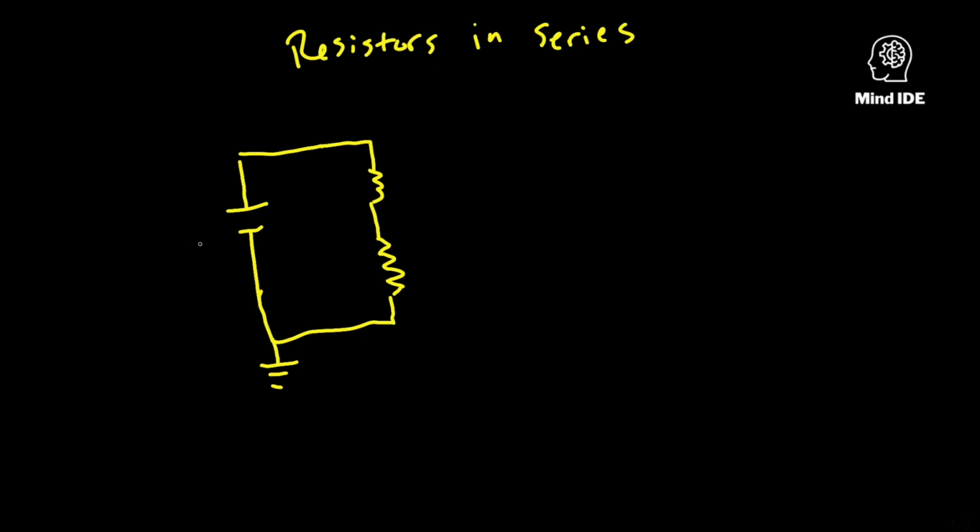So this is your voltage source right here, which we're doing resistors in series with a DC voltage. So you can think of this as like a battery. We're going to call this 5 volts. And then resistors are kind of this sawtooth looking thing. That's how you identify them in a circuit. So we'll make this one 1K, or here, just write it out, 1,000 ohms.